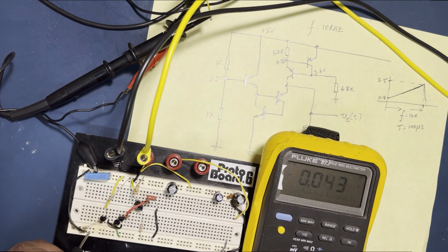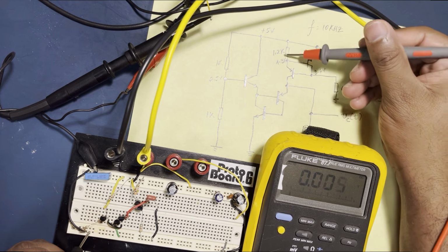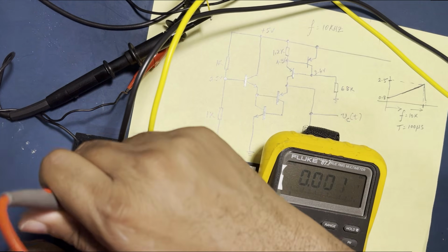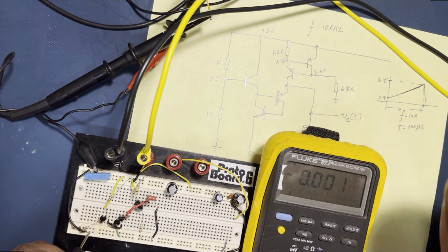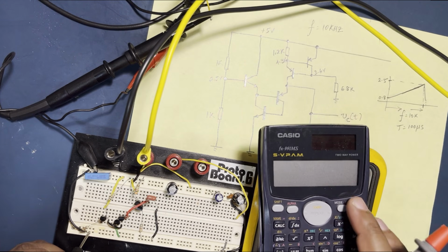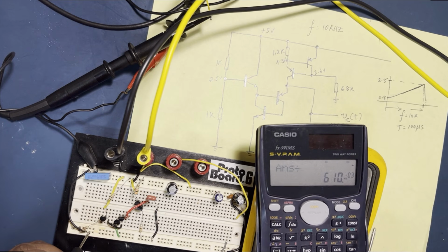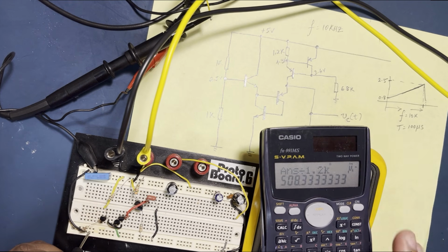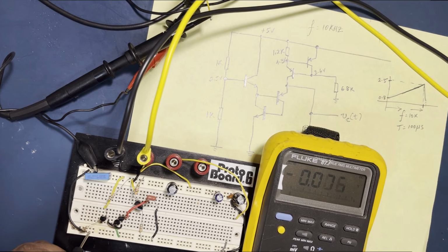Now let's measure the bottom of this current source setting resistor, the 2K and 3K in parallel. That would be this guy here. You can see I'm reading 4.39. We designed for 4.3, close enough. If we calculate the current, we measured 5 minus 4.39, divided by 1.2K, so about 500 microamps of current is flowing, not the 560 something that we calculated, which is fine.